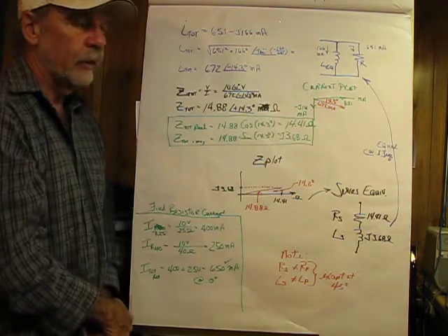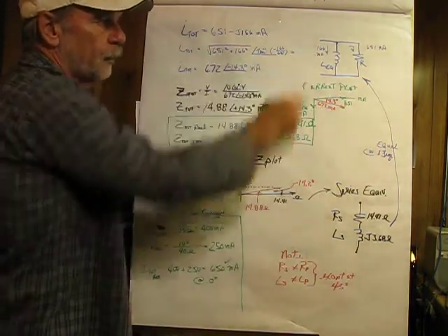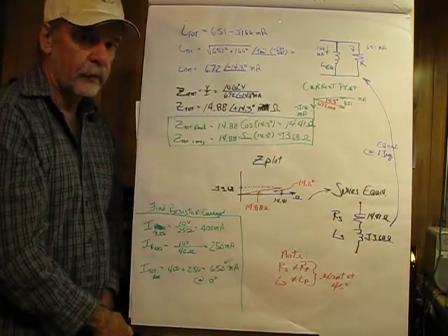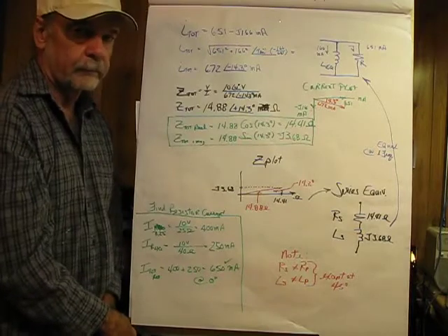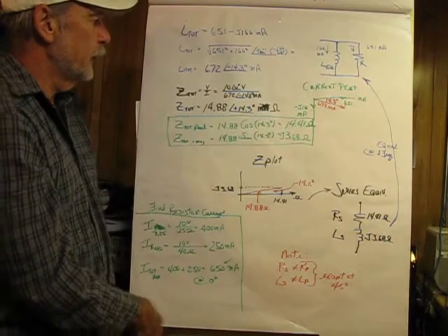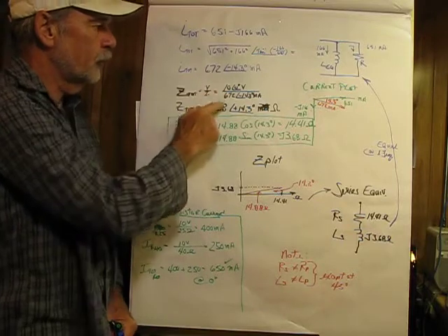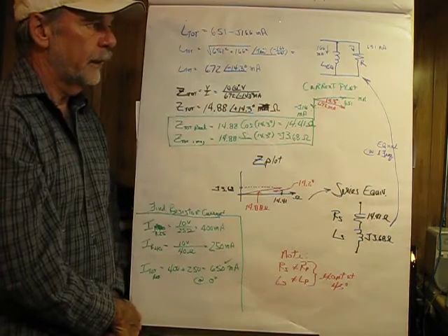Could we find out what that reactance value is? Very easily. Divide 20 volts by 166 milliamperes and you would have the inductive reactance of L equivalent. So our total comes up to be 672 at negative 14.3 degrees milliamperes.